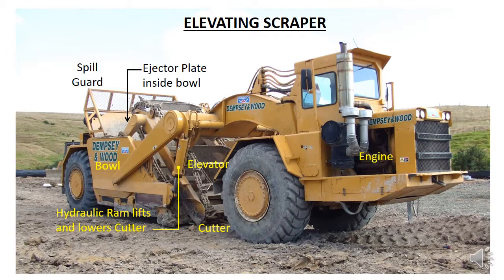The downside of having wheels is that they do not have as much traction as tracked vehicles. This means they may not be able to cut and load heavy or wet soils by themselves. In these types of soils, they may need the help of a bulldozer, which will push them during the loading of the material. This is called push loading.